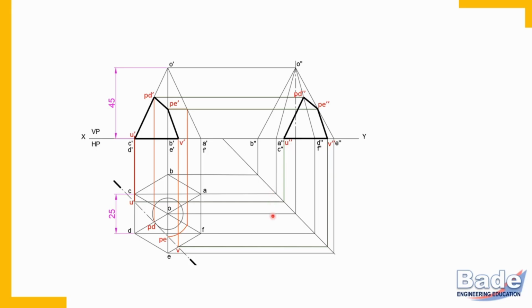Now make retained portion dark. Remember, the view in which cutting plane line, that view gives you clear idea about removed portion and retained portion. Portion nearer to observer is removed portion, make retained portion dark. All face edges or portion of face edges on the retained portion we have made dark. Now take help of this view to make other views dark.